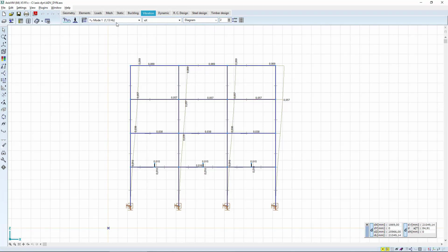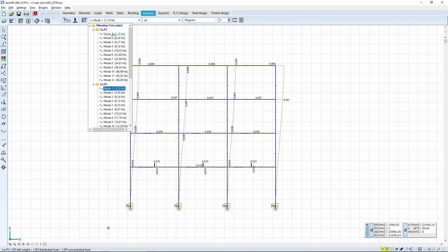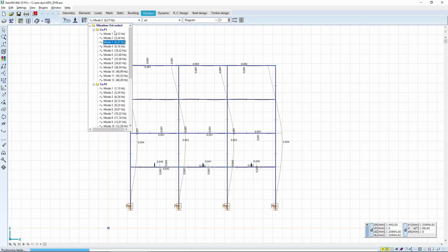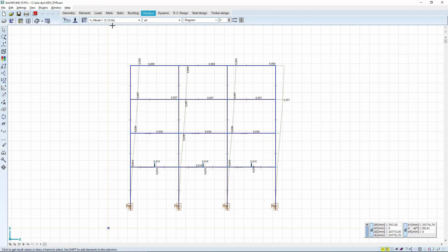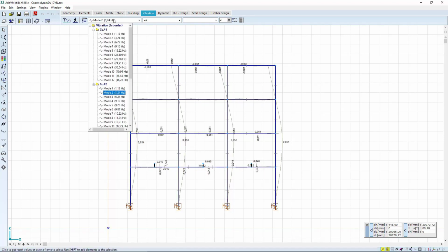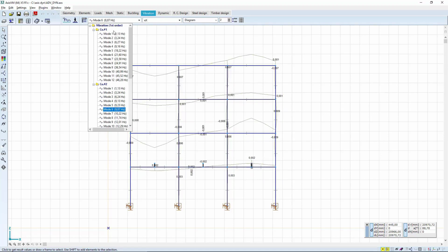Let's compare the mode shapes for each analysis. The results of the analysis are nearly identical considering the x-directional shapes. The main vertical displacements appear only in the higher modes. Based on the results, only the first 5 shapes are dominant.